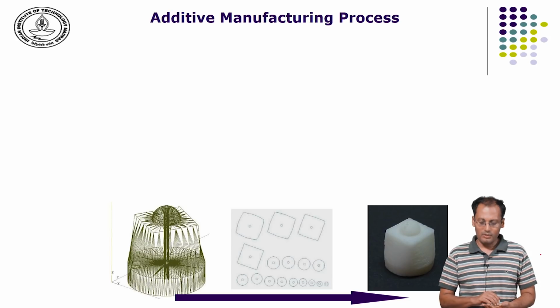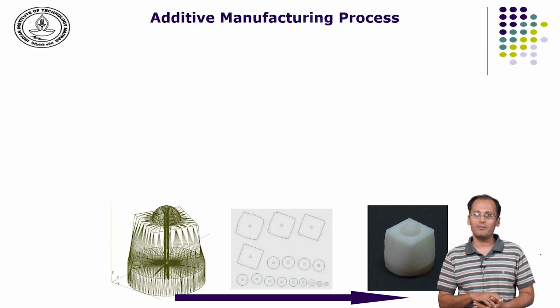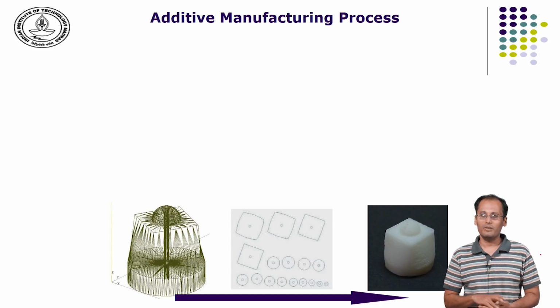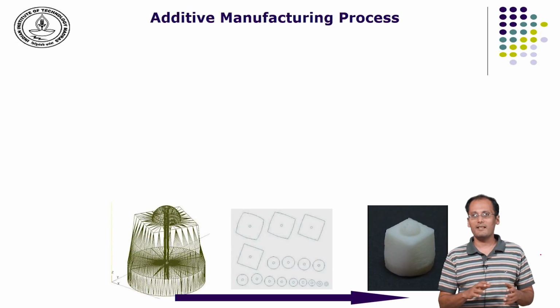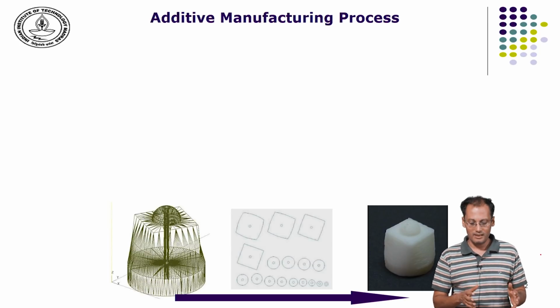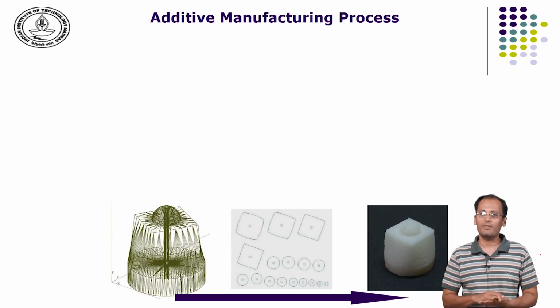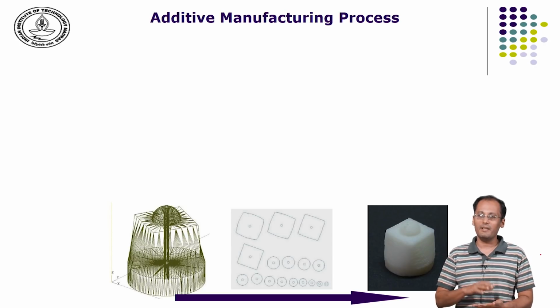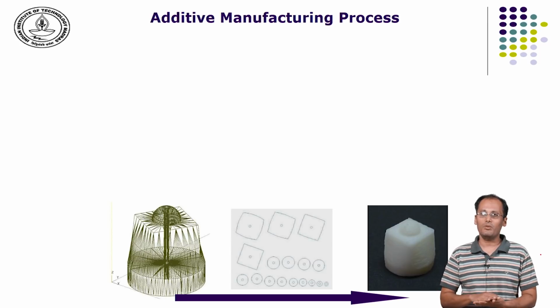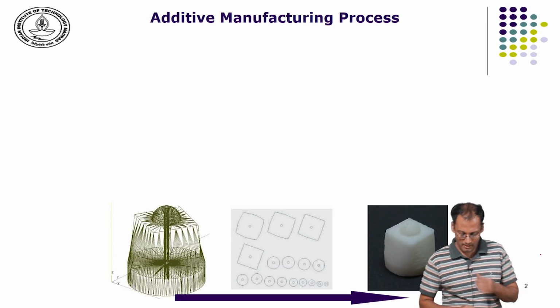The contours of the sliced model give the boundaries within which the model needs to be built. So, the boundary representation model as described by the surface model in the CAD is decomposed into a series of 2D models, thereby building one over the other to create the 3-dimensional part.